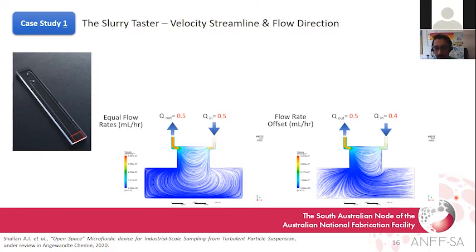Also, these results show the proof of concept for the device, and at the same time reveal why direct sampling doesn't work. If you look at the streamline, you will see the direct sampling doesn't work because the fluid has to come from the outside. So particles are drawn into the device. When you add an input flow, something like we did, this gets pushed out of the slit, which theoretically stops the particle from going in, but the fluid is still free to enter the chip.